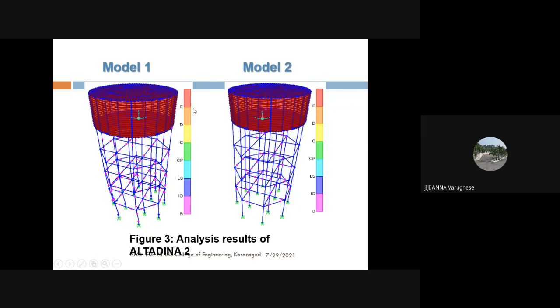And for the second time history, you can see loads of hinges forming in columns as well as beams. So this is not a desirable failure mechanism. We are not allowed a design which forms hinges in the column.